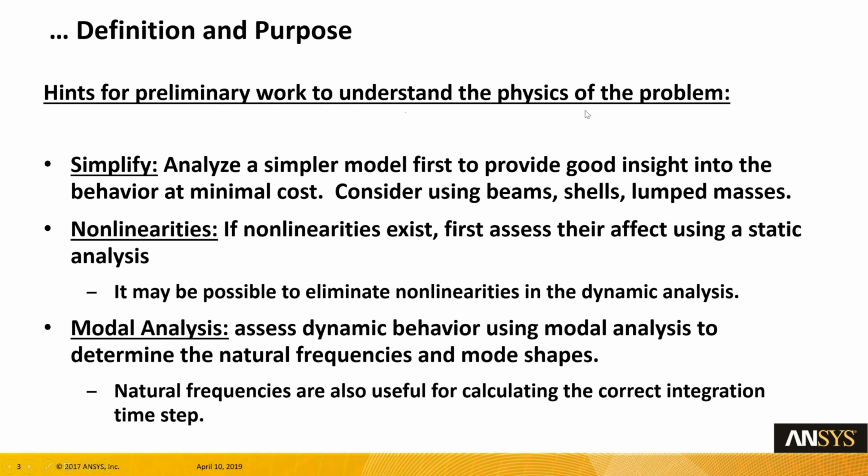Some hints for preliminary work to understand the physics of the problem. Usually, as engineers, we tend to jump into the most complex simulation. But before we jump into any complexity, we should try to solve and analyze a simpler model so that we know what to expect from a more complex model. If nonlinearities do exist, first assess their effect using a static structural analysis. It may be possible to eliminate nonlinearities in the dynamic analysis.